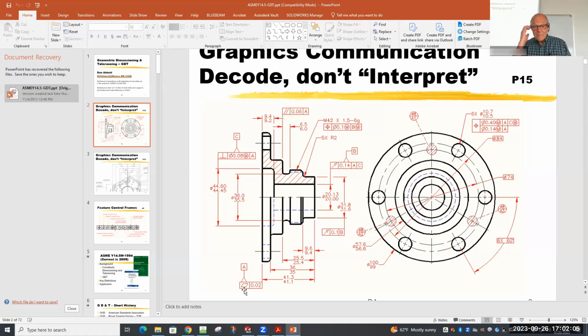Profile controls give you a little bit of an advantage, but the thing about a profile control is it actually lets you determine the direction the sandwich goes. Flatness just means you make a sandwich, and we don't care where the sandwich is, it's around that surface, as long as the surface falls inside it. Profile control says starting from perfection, you can only go this way, or you can only go this way, or you can go either one. But you can't do that with any other control.